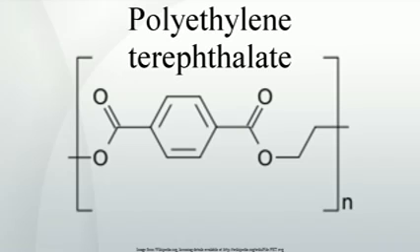Drying. PET is hygroscopic, meaning that it absorbs water from its surroundings. However, when this damp PET is then heated, the water hydrolyzes the PET, decreasing its resilience. Thus, before the resin can be processed in a molding machine, it must be dried. Drying is achieved through the use of a desiccant or dryers before the PET is fed into the processing equipment.